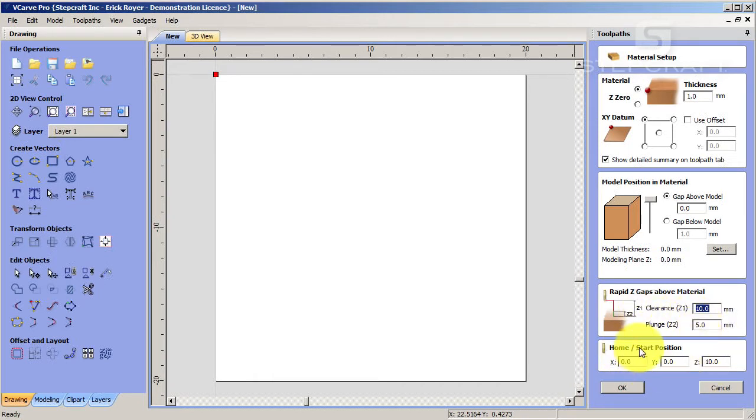First, the start position, it's going to start always up when we start working with any tool, but because it's the laser, we have a different height. We're going to set this to 0.0001. This is in millimeters. And also the clearance, we want almost nothing, so it's almost nothing. And the plunge, we want 0 movement on the plunge.